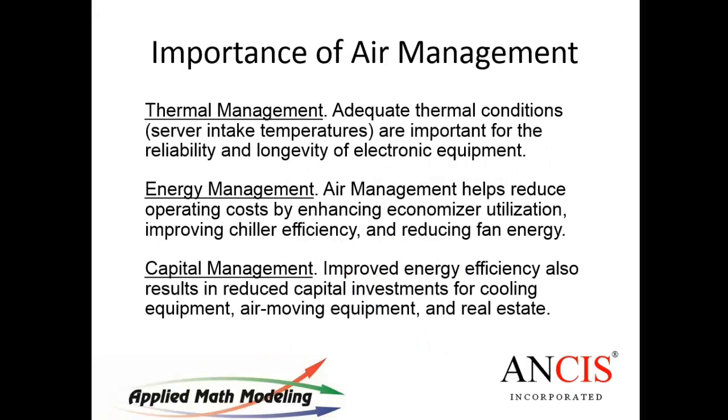So why is it so important to look at air management? Three key things. Thermal management: if you have decided to operate to a certain temperature range going into your servers, air management is the tool where you can actually arrange it to be within that range. The second is energy management. Like I mentioned, if you're supplying too much cool air to your space, you're kind of killing the efficiency of your cooling system.